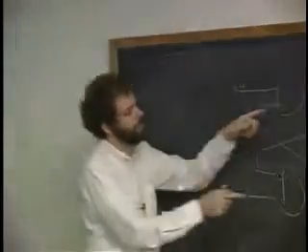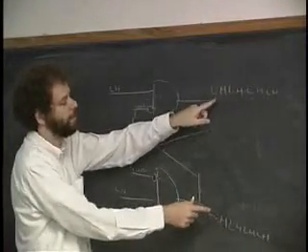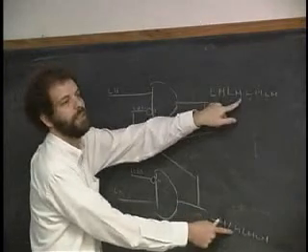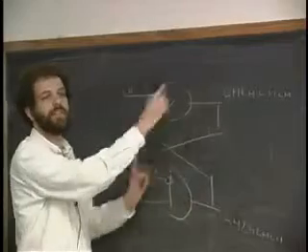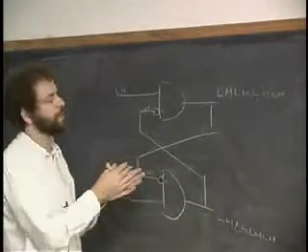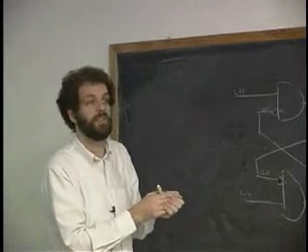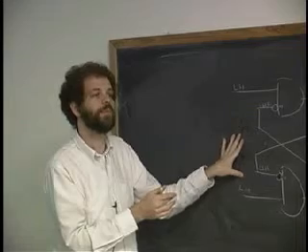Now notice it's not really making up its mind in either of the cases. It keeps flipping back and forth between no one won and everybody won, and no one won and everybody won. And the ones and the zeros are chasing each other around in this loop, which is just a weird thing, but it can happen. And circuits like this, in fact, if you hook an oscilloscope up to them, can oscillate.